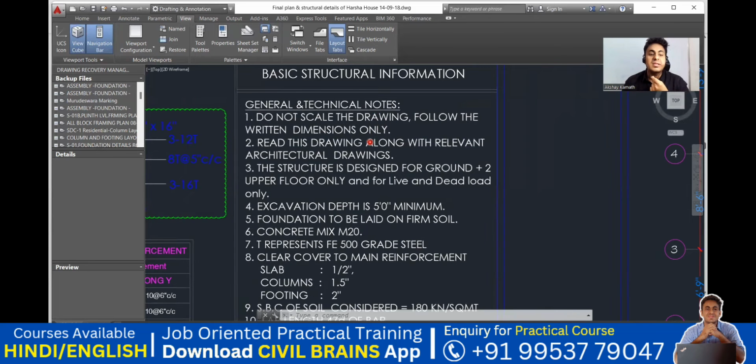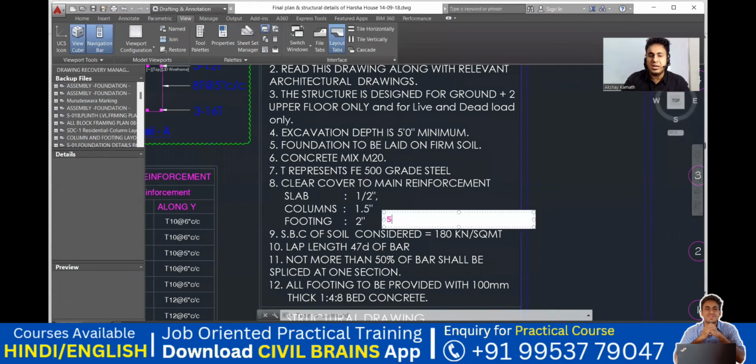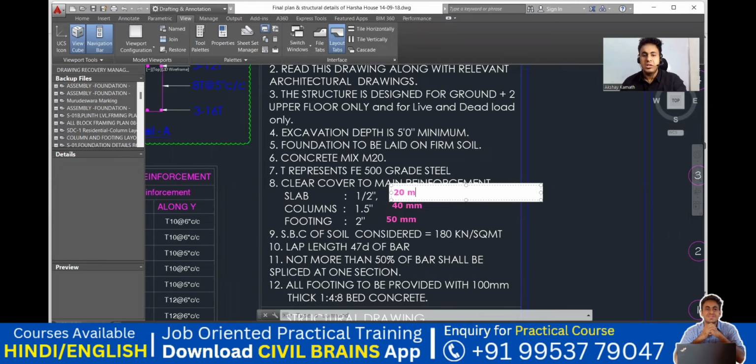Other than that, these are the covers we are supposed to give. For the slab, it is half inch, which comes out to be around 12.5 mm. For the column, it is 1.5 inch. And for the footing, it is 2 inches. 2 inches comes out to be 50 mm. So I'll put it in terms of mm, so it is easy for us. Footing is 50 mm. Column is 40 mm. And for the slab, it is usually 20 mm. Even though they have mentioned half inch, it's okay. It is 20 mm.